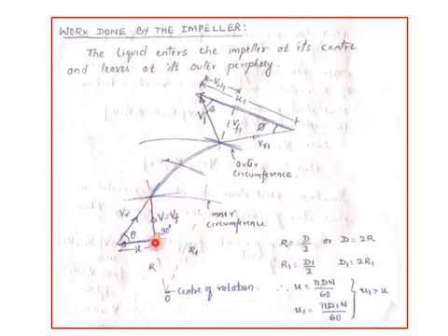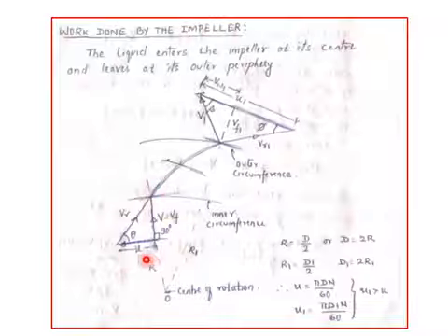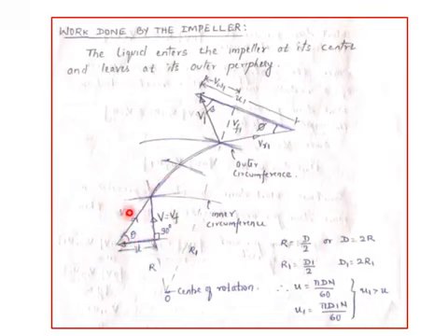Now, you know that by the time the water hits the vane, the vane would have moved with some velocity. So the water actually strikes with velocity Vr, which is entering in the tangential direction to the vane. You can observe that the vane is moving in this direction, the jet is striking in this direction, so the jet has to enter in the radial direction, that is V is equal to Vf. So now we always get a right angled triangle in the case of pumps at the inlet. The angle of Vr is always theta. So when they say that the angle of vane at inlet is theta, here beta is always 90 degrees.